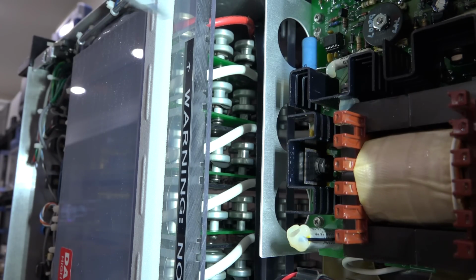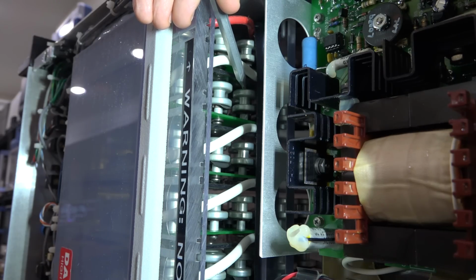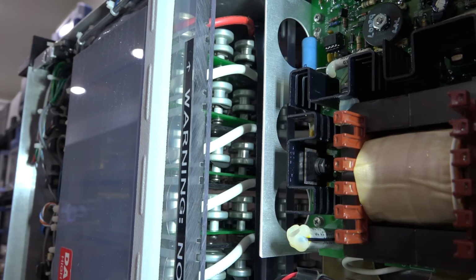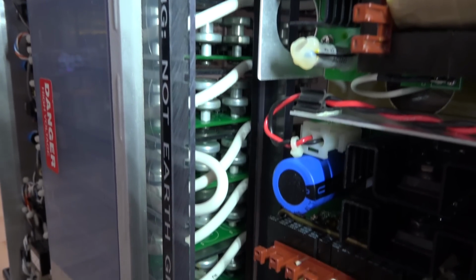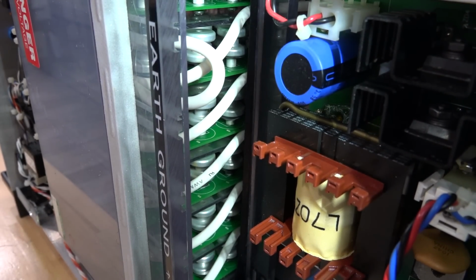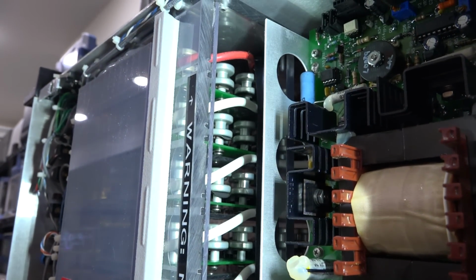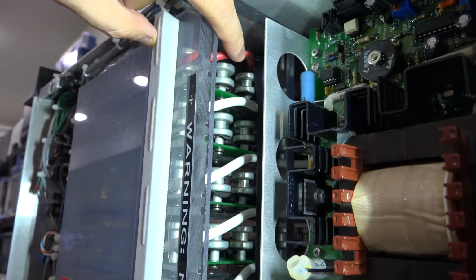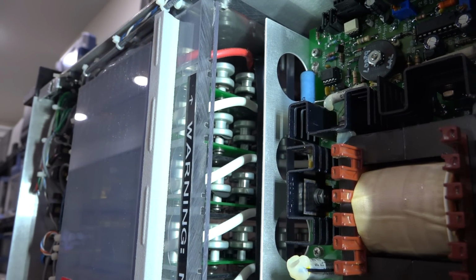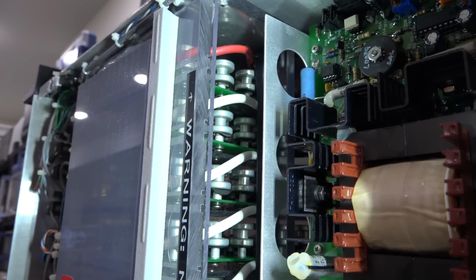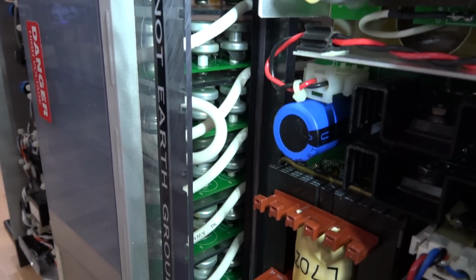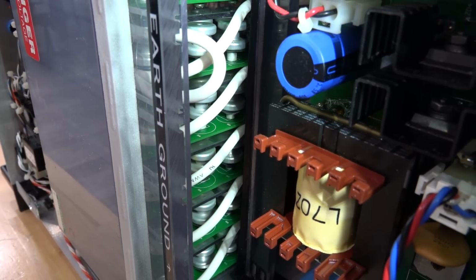Now looking from the other side, you can see the highest voltage section a little bit better. And these pillars that you see, aside from being a good high voltage isolation and arcing and so on, they're also heat sinks from the final stages, I think. Yeah, if you look over, you can see all those white wires are the wires that connect the final output together across all the different vertically stacked stages. At the very top, this line over here has come from the power supply, probably the positive one. And at the very bottom, there is an equivalent one. We'll look at the other side of the instrument so you can see a little bit better, because you can't see the output network very well from this side. But yeah, everything totally handmade.